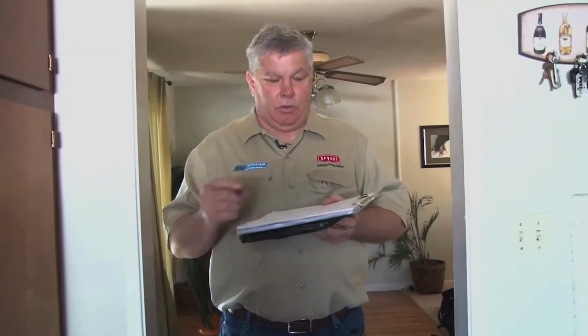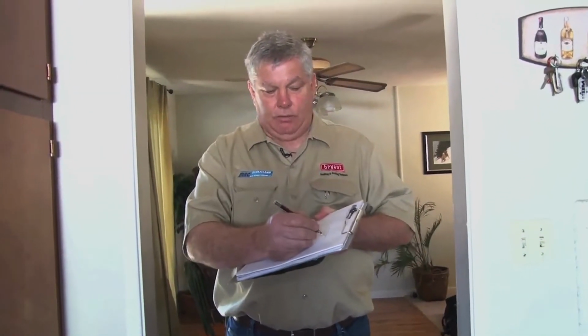When I start my drawings, I like to always come in and go in one direction so I can walk basically in a circle around the house and I don't miss any rooms. So as I came in the door, I'm going to start over here to the left, and the first room off the living room is the kitchen. I make a basic plan, draw the footprint of it, and then I draw in any windows that we might have, because that's got to figure into my load calculation.